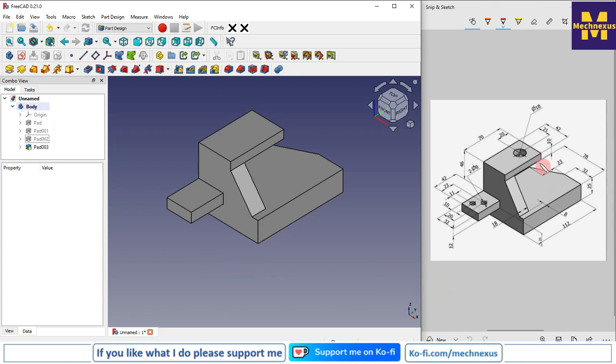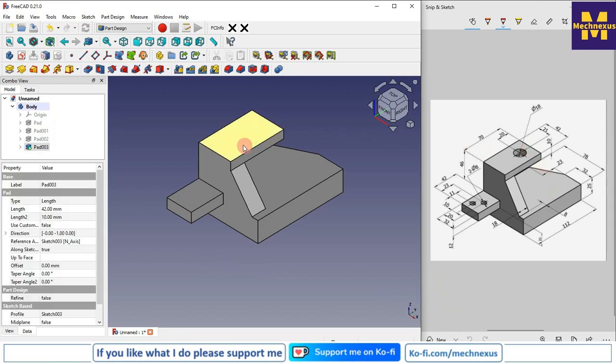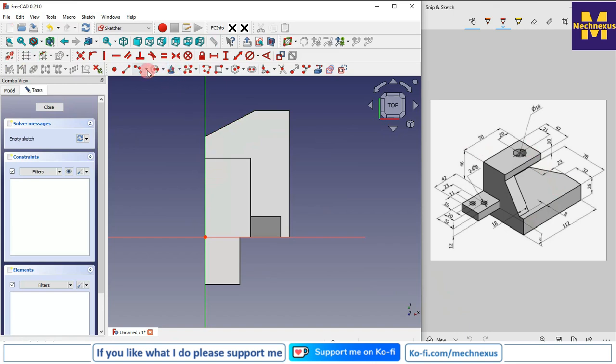And now we will create this hole. So for this we will select the face, click on the sketch, click on the project geometry, select these two edges and project, and this hole is of 18 mm.